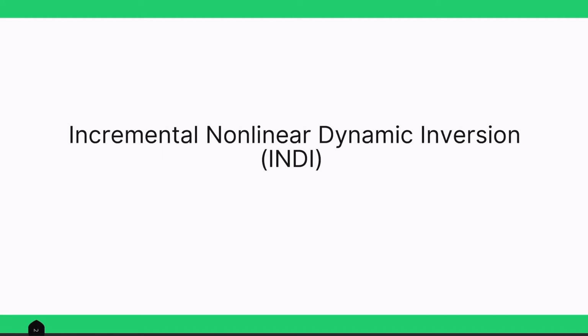Today I'm gonna discuss the incremental nonlinear dynamic inversion control method, or simply INDI. As we know, aircraft don't always behave like linear systems. In some flight regimes or in some failure scenarios, they behave in a nonlinear way. To control them, you therefore also need a nonlinear controller. And this controller should be as robust as possible, for the model never exactly matches reality.